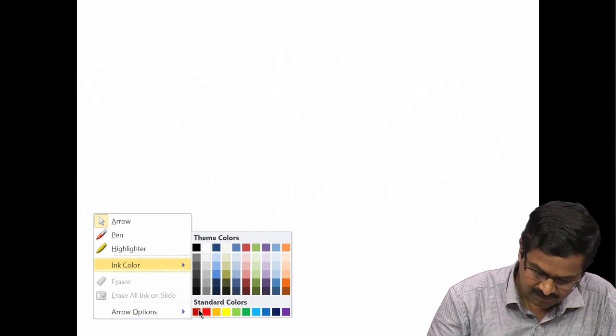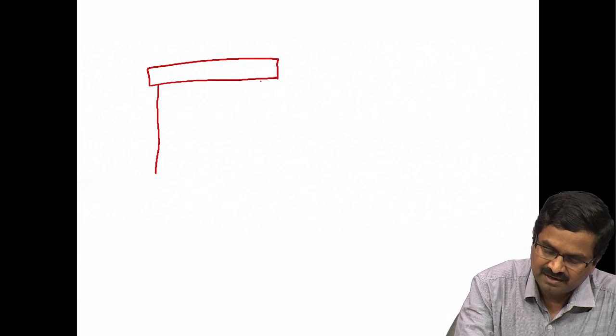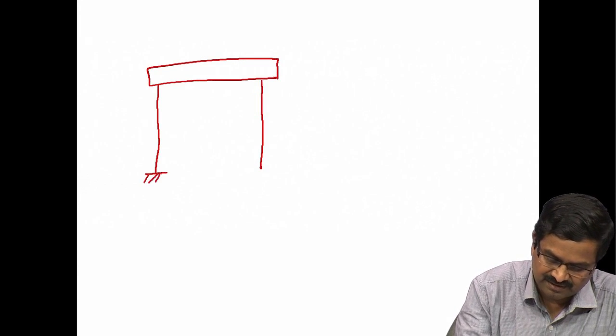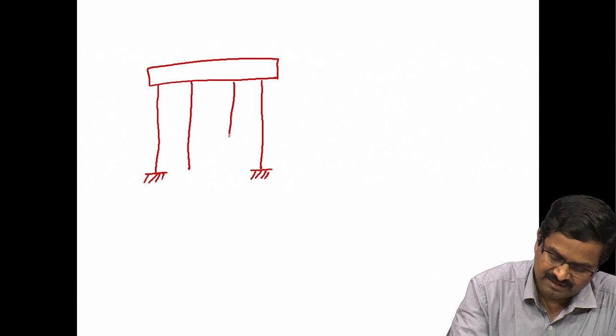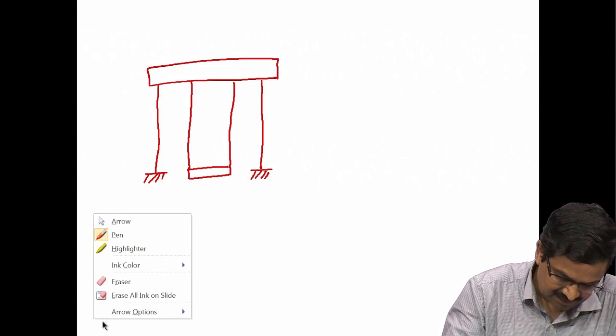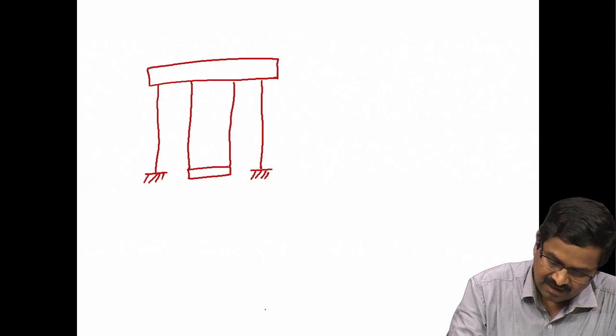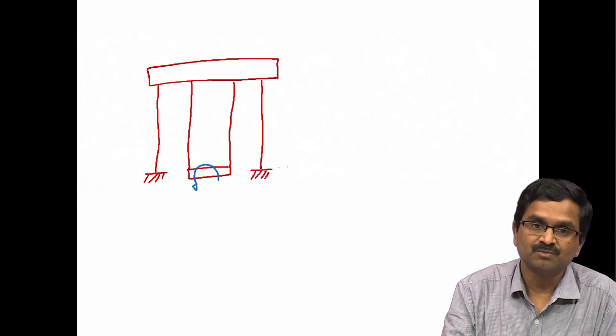So, let me just draw that. Okay. So, now we have that beam, and this top block is there, and another beam, and this is fixed here. That is the parallel motion stage. Now, we have 2 more things added, and we have this block here. What I am saying is that what we just ran is applying a moment load on it. When we did that, instead of purely rotating, it also moved in the x and y.